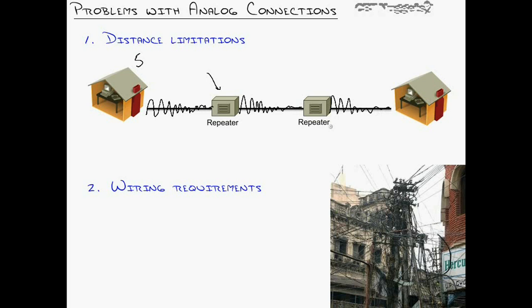Anytime you regenerate an analog signal, it does regenerate the original waveform stronger, but these repeaters are dumb devices. They don't have the ability to differentiate between just white noise on the line, noise introduced through transmitting over that wire over an extended distance, and the original voice that was sent. So the more times you regenerate that signal, the stronger and stronger that white noise gets.